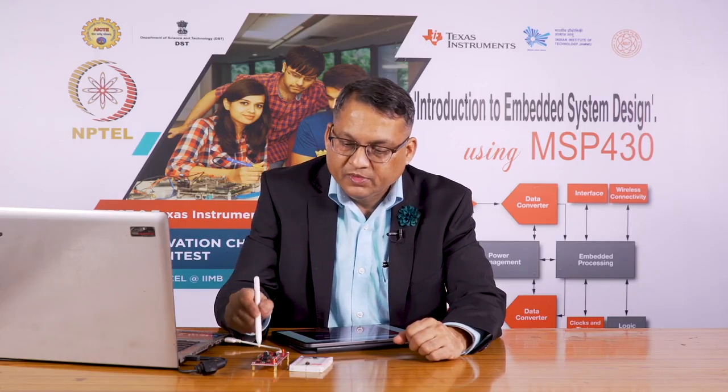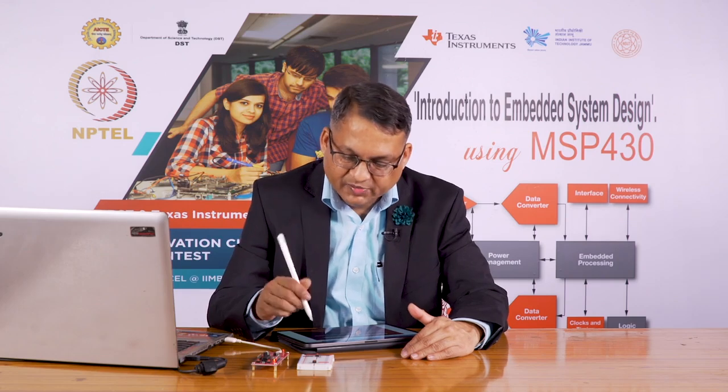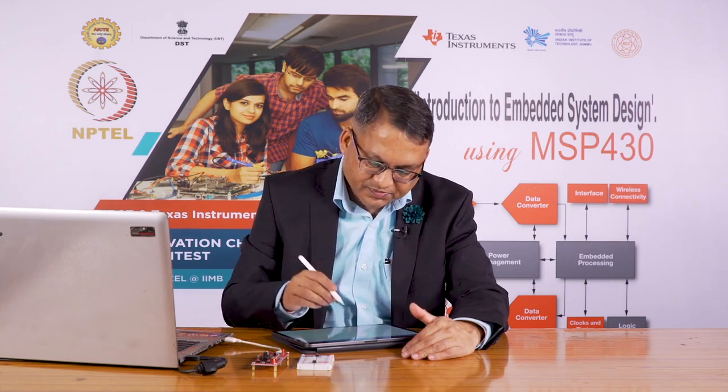Let us now move over to our hardware configuration, where we have this laptop. We have also connected the MSP430 lunchbox. There is a switch on the lunchbox already connected to P1.3, but we want to illustrate how we could utilize the internal pull up and pull down resistor configurations. We have a breadboard here. On this breadboard there are two switches which have been configured in the pull up and pull down configurations, meaning we have a switch where two terminals of the switch are available here.